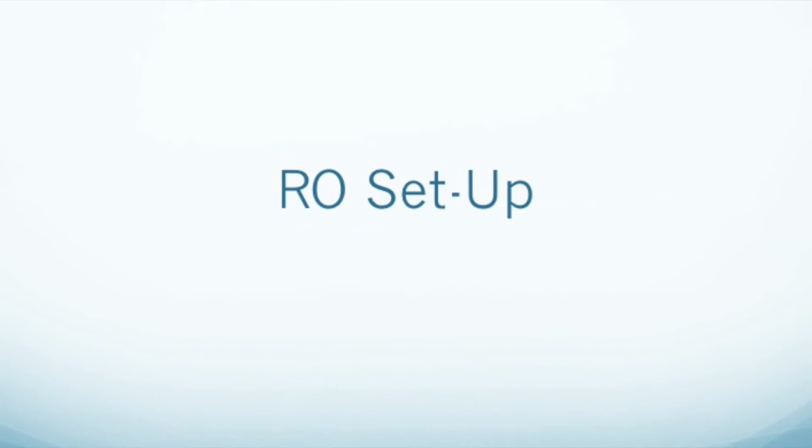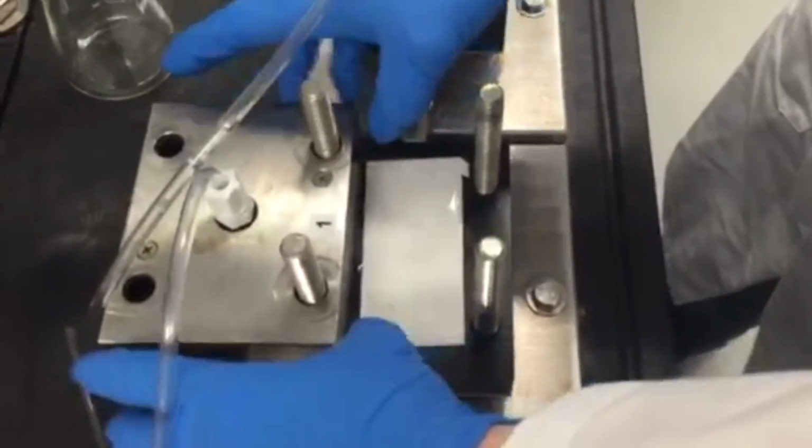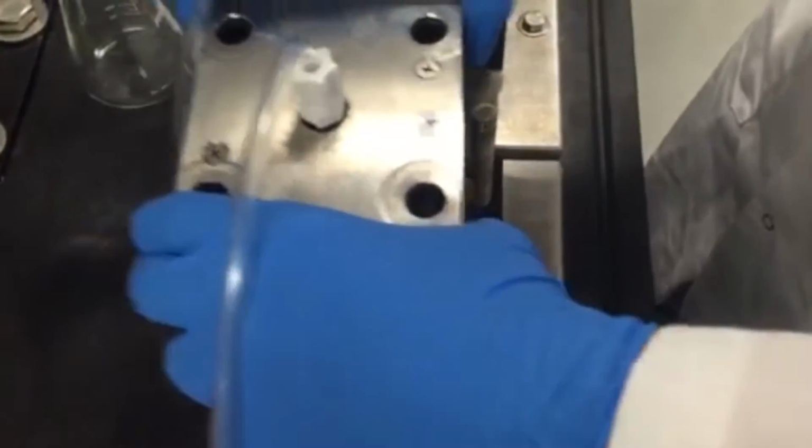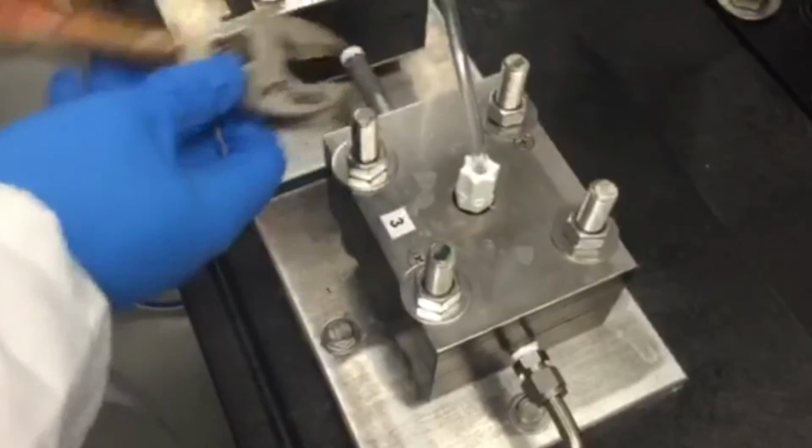The first membrane to test is NF270. Load each membrane into each cell with the shiny side facing down. Place the top half of the cell on the membrane and load the designated washers and nuts onto the bolts. Tighten with a wrench in an X fashion. Record the mass of each of the graduated cylinders. Place the permeate outlet tubes into a designated outlet beaker.